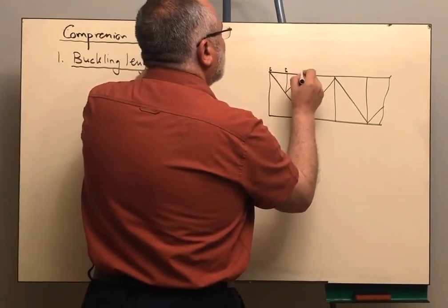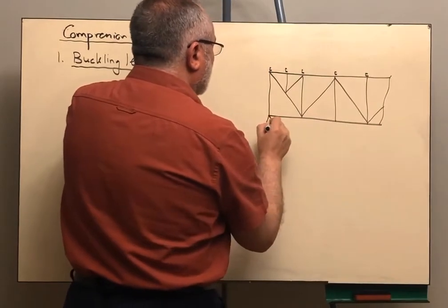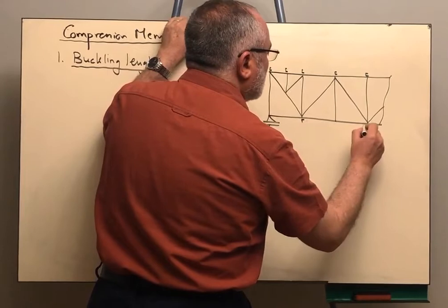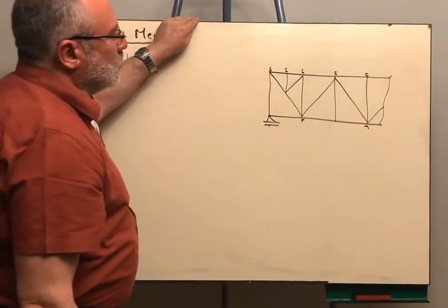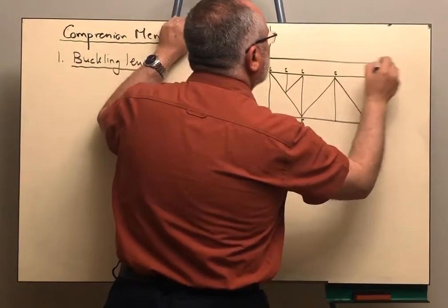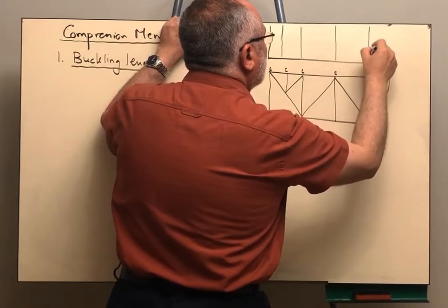These are the roof purlins, and we are having here struts connected to the truss at the bottom chord. The shape of the upper bracing will be like this.